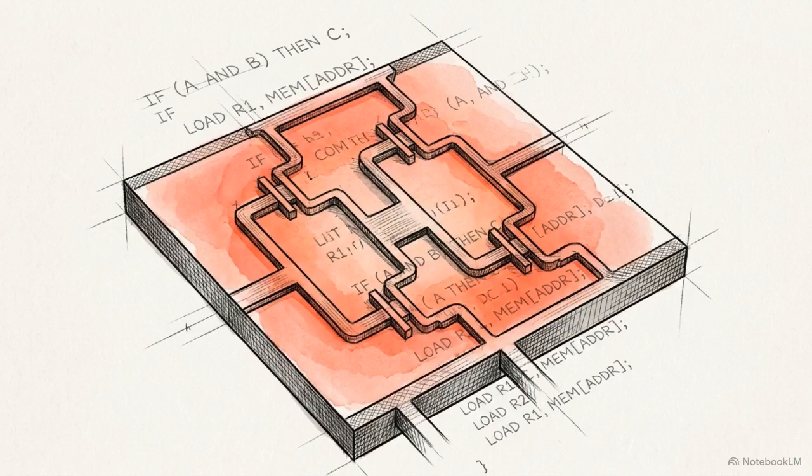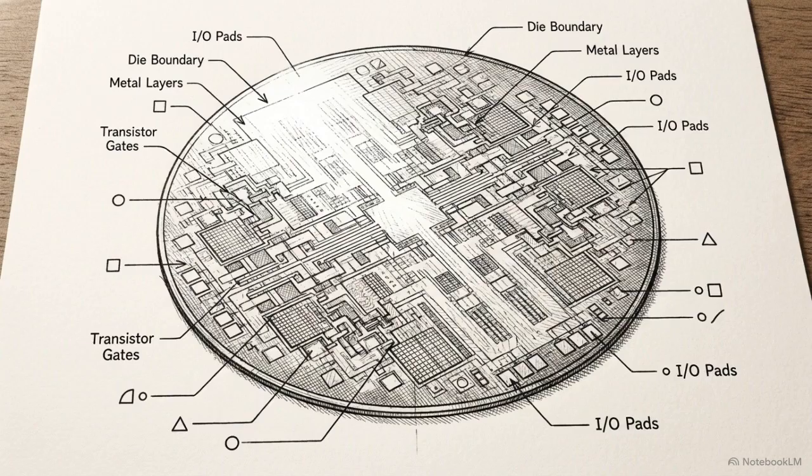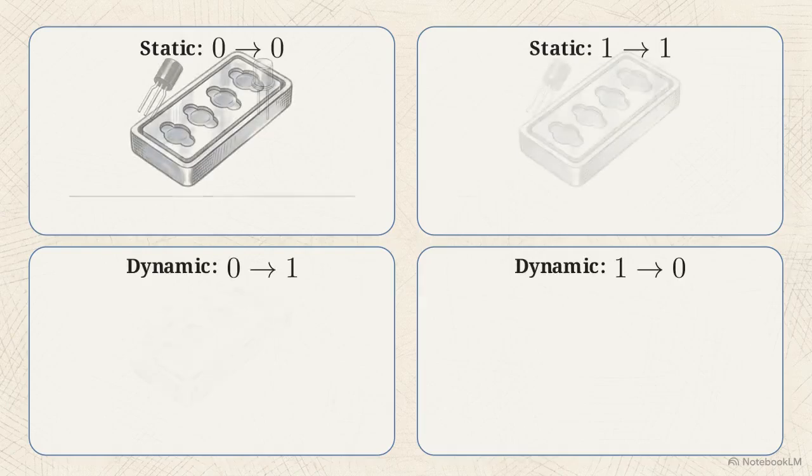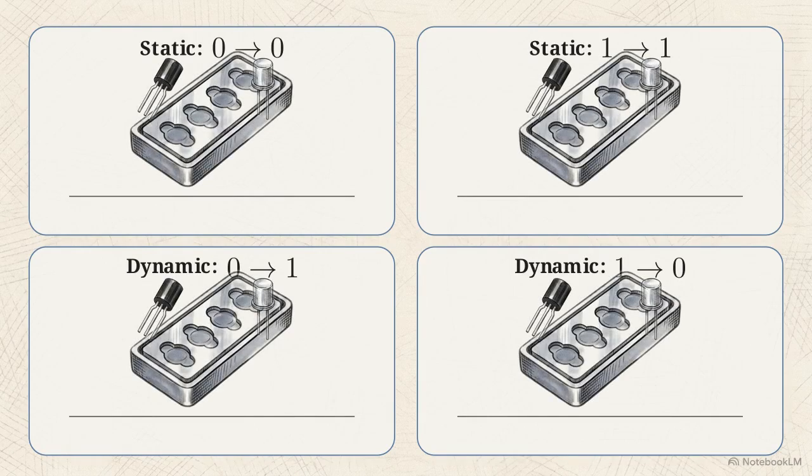While software-level countermeasures like shuffling or masking can introduce algorithmic obstacles, they do not change the underlying physical behavior of the gate. As long as the logic gates themselves broadcast their state to the power supply, the physical foundation of the system remains transparent to an attacker. This standard static CMOS logic gate is modern computing's baseline and the root of power leakage.